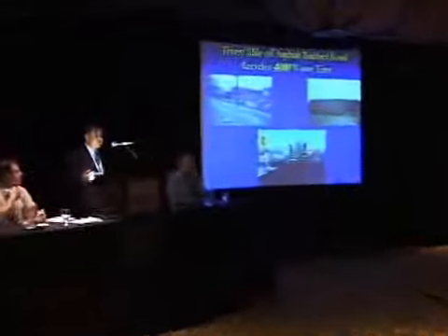So the passenger tire equivalent, what basis is that 3 tires passenger tire equivalent on? Based on 10 pounds of crumb rubber per PTE, because what we know, there was a presentation this morning where we were talking about 20 pounds per PTE, but most passenger tires are rated at about 18 pounds. You're looking at about 10 pounds of recovered rubber per PTE, or 30 pounds of crumb rubber for 1 ton of asphalt. So if it's 2,000 tons of the mix, based on 1.5%, you're looking at about 30 pounds of crumb rubber per ton. Okay, thank you.